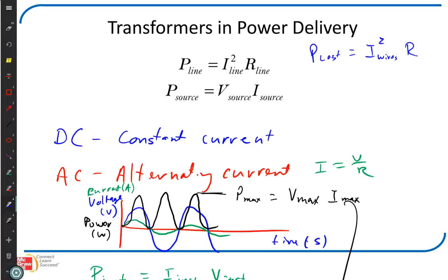It's going to decrease by the same amount because the transformer has the ratio of voltage and current such that you have ideally no loss in the transformer. So if I raise the voltage by a factor of 1,000, I lower the current by a factor of 1,000. What's that going to do to the power loss? It's going to lower by how much? By a factor of 1,000,000. So by raising the voltage a factor of 1,000, you decrease the power loss by a factor of 1,000,000.